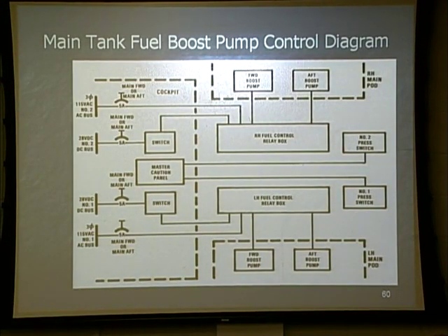When we talk about the main system, now this is nice to see. Reality is, are any of you going to remember this? Nope. It's just so that you can see the checks and balances with the relay box and how it actually activates. When you turn on the pump, when you turn on the switch up in the cockpit, here's what's going to happen. You'll notice that it's 28 volts DC. In this case, we've got the number 2 system on the right side. You'll notice that it pulled 28 volts DC, but it's also pulling 115 volts AC.